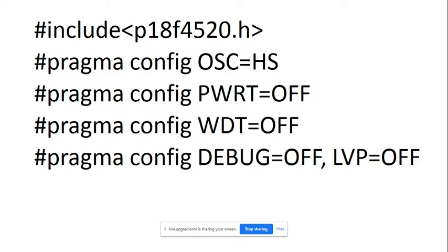It takes some time to reach that point, which means there is a settling time. Up to the settling time, your controller must be held in reset for a more accurate result. In some applications accuracy is very important, and in that case you turn on PWRT, but right now we are doing normal practicals, and that's why we are not using the PWRT function.